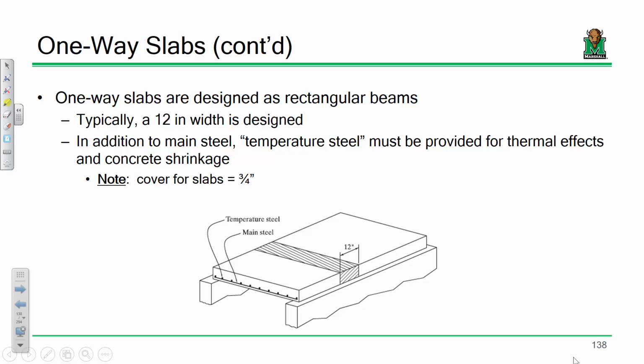So what I do in slab design is I look at a small strip of that slab. Typically, we take the strip to be 12 inches wide, like 1 foot of slab. And we'll design, okay, what is the deal with the reinforcement inside that 1 foot strip?